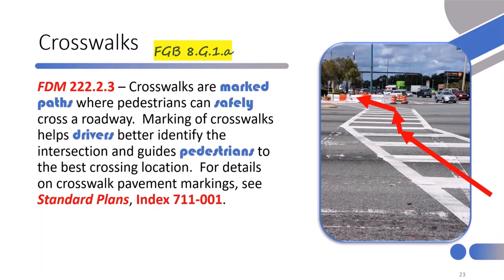So ideally, we'd like to see crossings with a tangent alignment. And if there must be a change, for example in the center refuge island or the median, at a hardened center line or bullnose, then we would definitely encourage the addition of some sort of tactile or non-visual, physically detectable element to communicate that change in alignment.